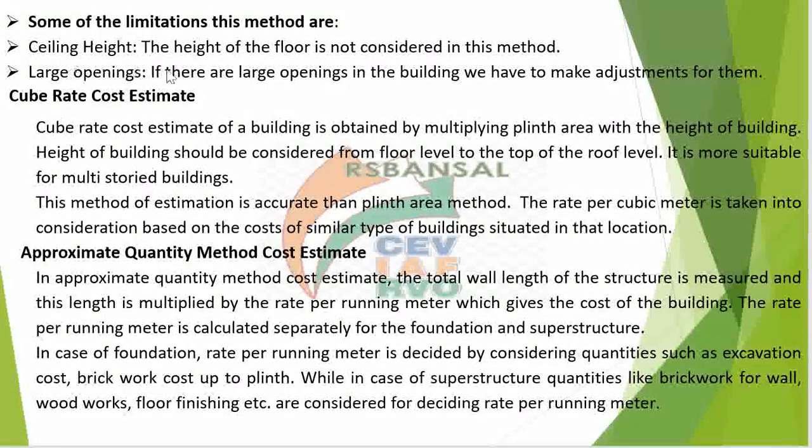If the subject building of which you are doing valuation has a different height, then you cannot use the available plinth area rate for a particular specific height. Second thing, if there are very large openings in the building, we have to make adjustment for them.